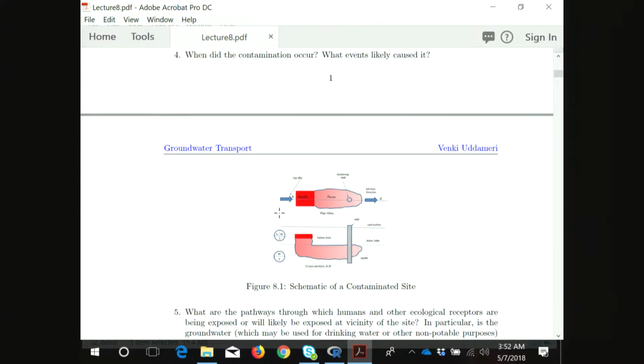Okay, so a receptor in risk assessment is an organ in your body or something in your body that gets attacked by that contaminant. So a receptor point is where you start getting exposed to that contaminant. So a well would be a receptor point in groundwater, and similarly you could have non-point receptor points like air. If it's air pollution, it's there everywhere, so an intake of a water treatment plant in a surface water stream is a receptor point.